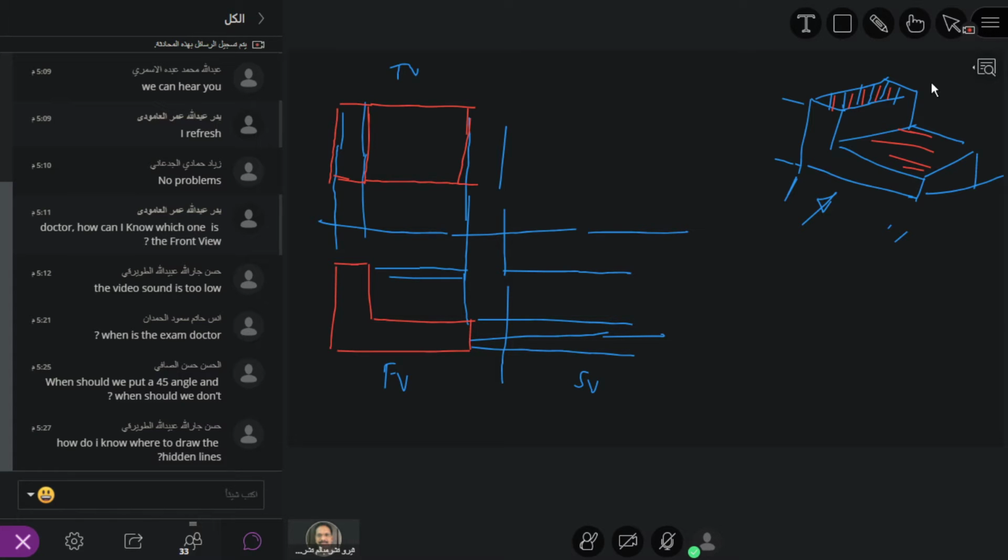All right. So now what should I do? Here only now you must be careful. From the center here, you draw a 45-degree angle, and now you extend this line, connect this line, then you extend all the way here, so that now this width, whatever width it is, will be the same here.